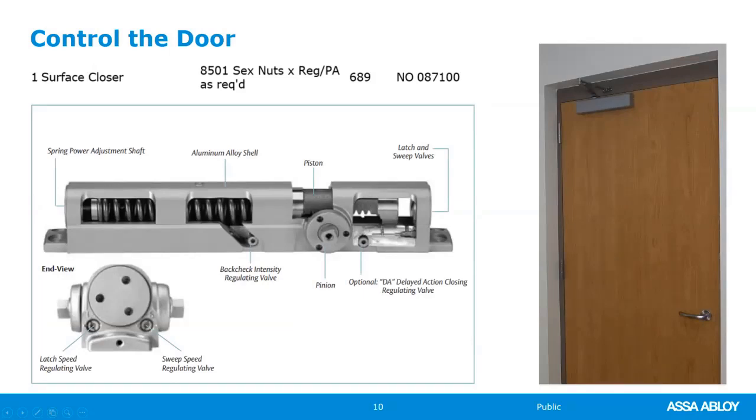You do need to detail this if you're writing the submittal so that the contractor mounts the door closer on the proper side. The DHI, the Door Hardware Institute, teaches the rule of thumb that we keep door closers on the inside of rooms, inside of stairs, and not in the corridor itself to every extent possible. There are some exceptions. We'll talk about those exceptions tomorrow. But for the most part, we try to keep the closer on the inside of the room, on the inside of the building, inside of stairs.